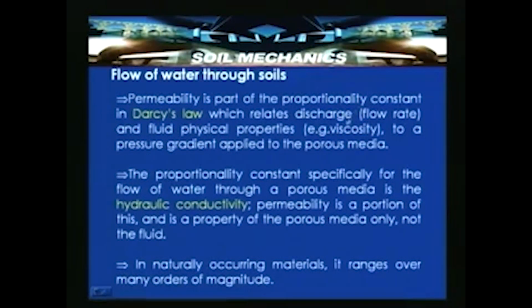Darcy's law remains valid. Darcy's law relates the discharge, that is the flow rate, and the fluid physical properties like the viscosity of the permeant under consideration, to a pressure gradient applied to the porous media. That means at what head the flow is taking place, that is the head loss or a pressure gradient. The proportionality constant specifically for the flow of water through a porous media is hydraulic conductivity. So, permeability is a portion of this and is the property of the porous media only, not the fluid.